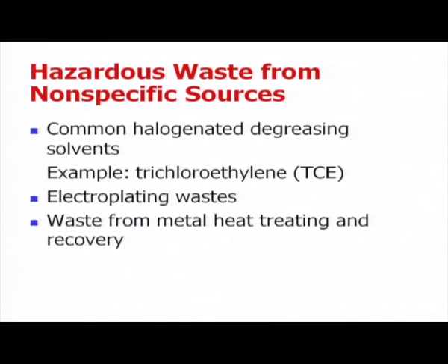And some of the hazardous waste from non-specific source also likely to come. For example, common halogenated degreasing solvents. For removing the grease, we use normally organic solvent, especially halogenated solvents, dichloromethane type of things are used. Remove the grease in any objects, especially metal, and this is a hazardous waste again. Trichloroethylene is one such thing. And electroplating waste and waste from metal heat treating and recovery plant. So, all these things are hazardous waste from non-specific sources that also has to be managed as hazardous waste.